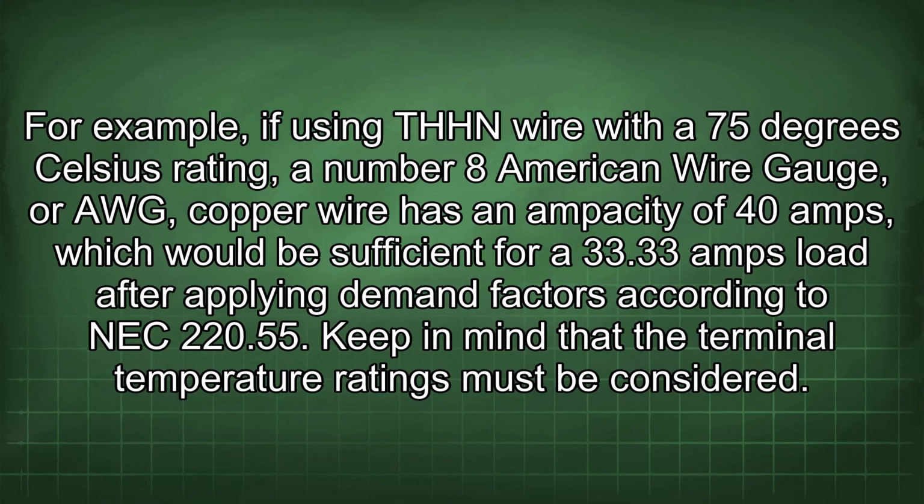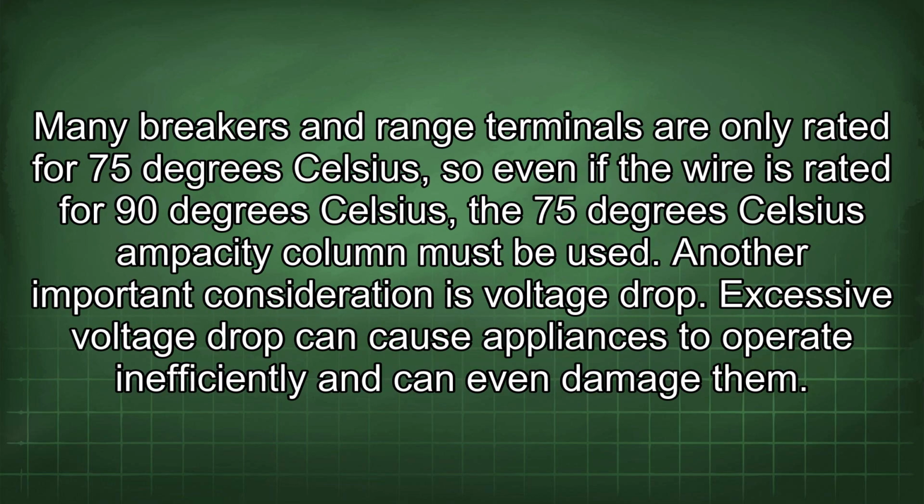Keep in mind that the terminal temperature ratings must be considered. Many breakers and range terminals are only rated for 75 degrees Celsius, so even if the wire is rated for 90 degrees Celsius, the 75 degrees Celsius ampacity column must be used.